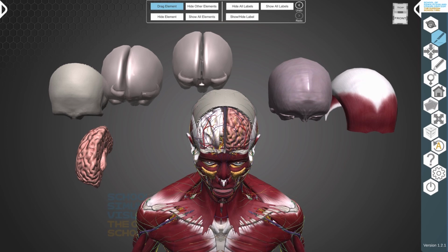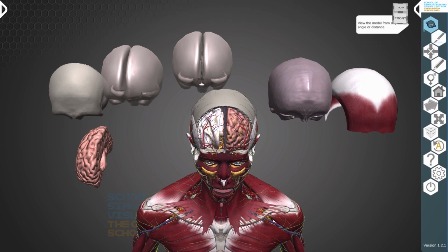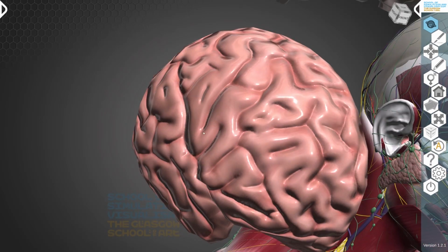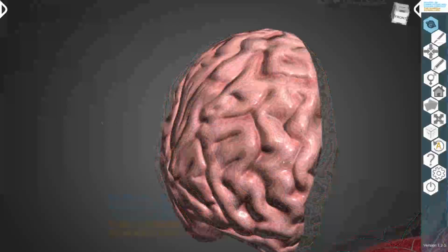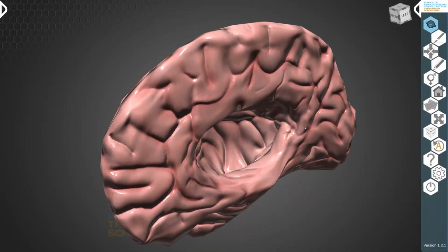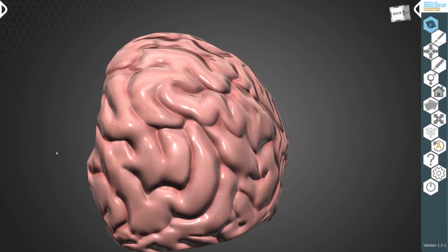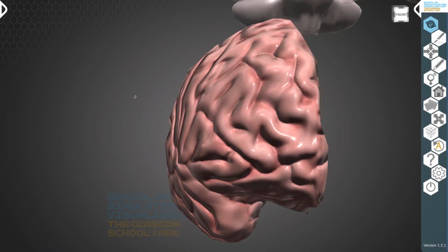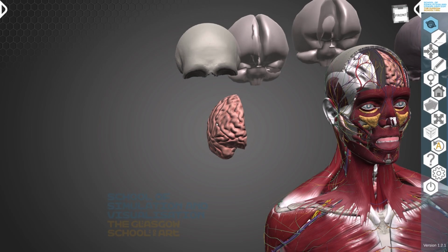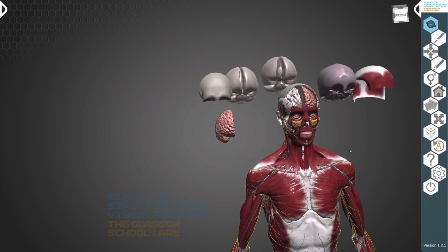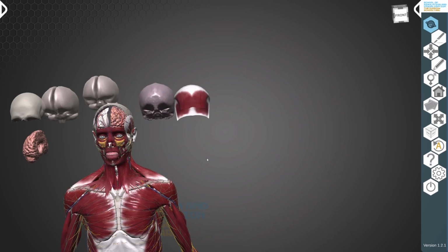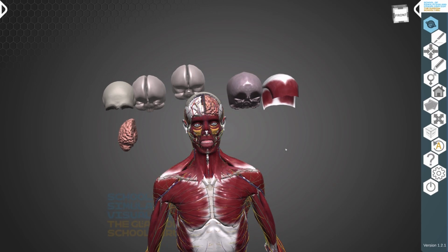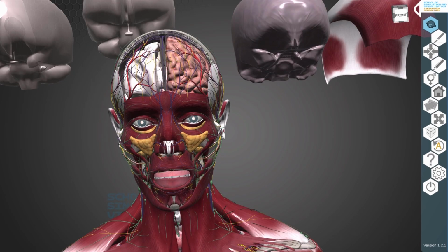Now if I click my camera up here again, and I double click, then I zoom right in, and then I can rotate. Because I've double clicked, my rotation point now is whatever anatomy I've just double clicked. I'm going to zoom out again with my middle mouse button. And then I'm going to pan the screen into the middle. Scroll in a little bit. There we go.